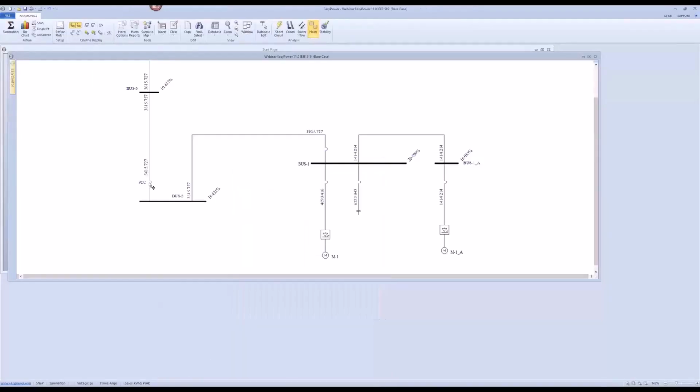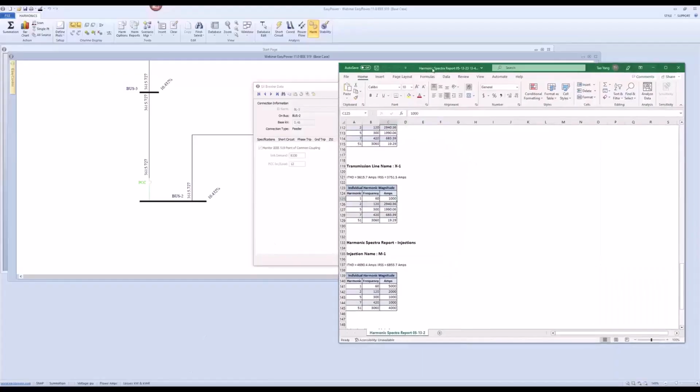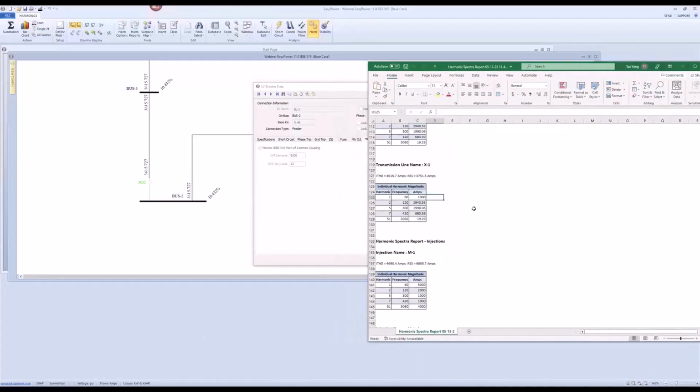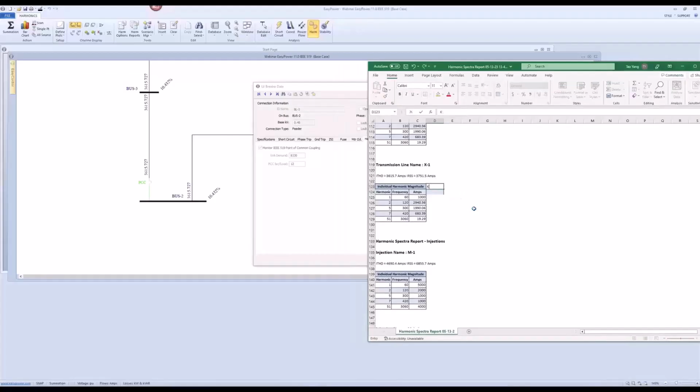Where is my load demand? My load demand is what I entered over here, right? 8330 kVA. What's my voltage? My voltage is 0.48. Okay, you got your kVA, you got your voltage. Then you calculate your load current based on that, right? It's actually calculated. We just saw that from power flow already. So I'll just make it simple. The kVA demand is equal to 8330. My kV is equal to 0.48.